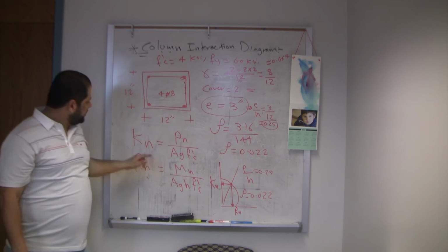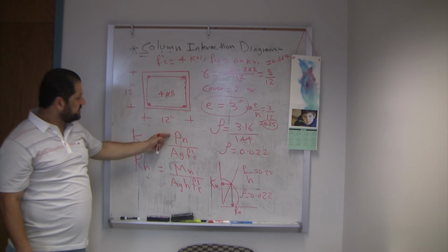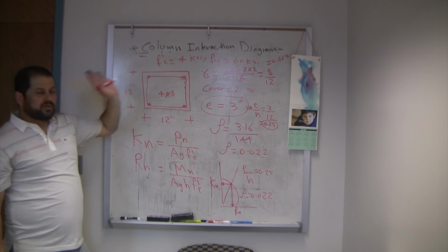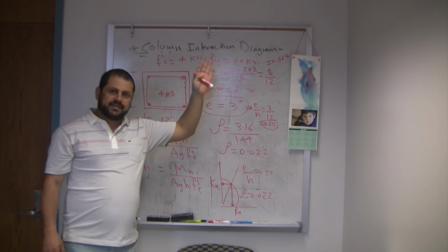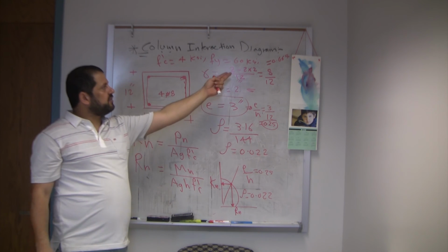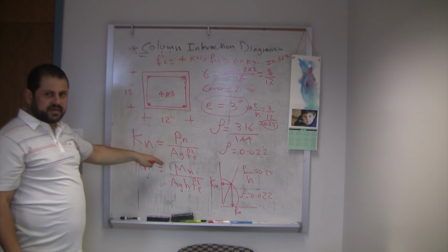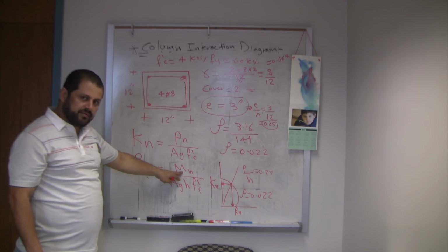Once you have Kn, you multiply by 144 times 4 to get Pn. Then likewise, go to gamma equal 0.6, get Rn, then go to gamma equal 0.7, get Rn. For your case, gamma equal 0.667, get Rn from the linear interpolation.